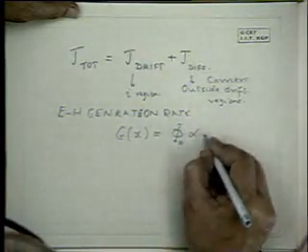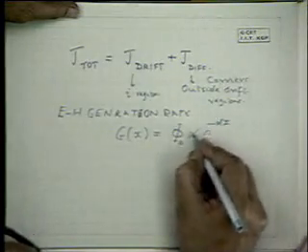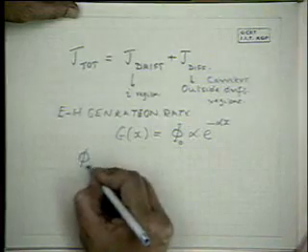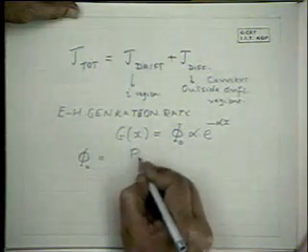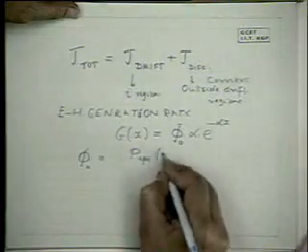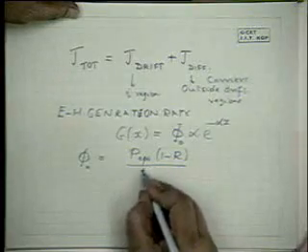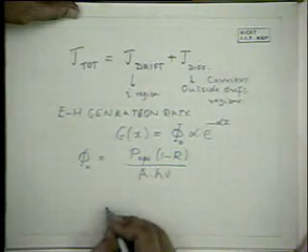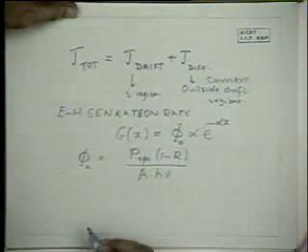The intensity of the light at a point x is phi 0 e to the power minus alpha x, times alpha. Where phi 0 is the incident photon flux per unit area, that is just P opt (1 minus R) divided by area, and the energy of a photon is h nu. R is the reflection coefficient, A is the area. If it is monochromatic, it is h nu.